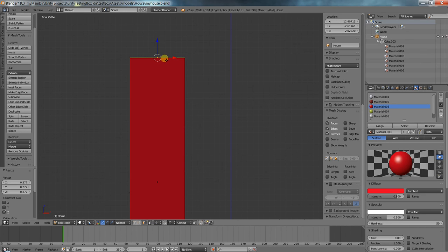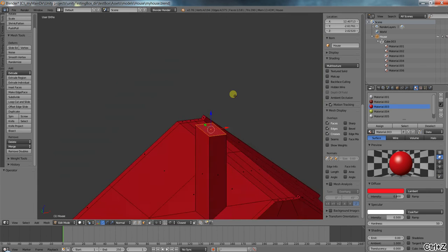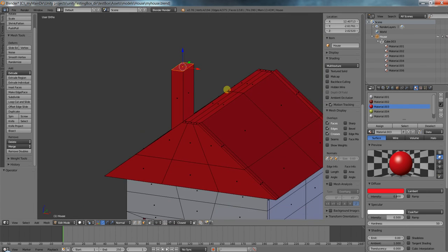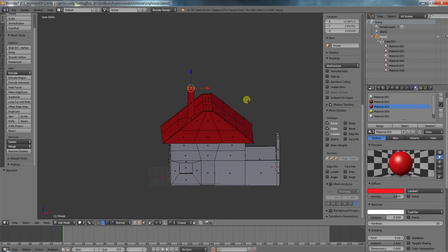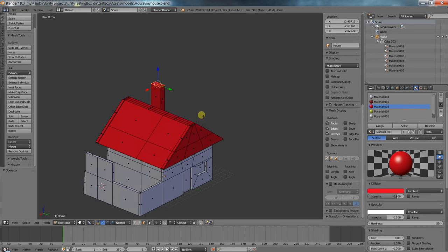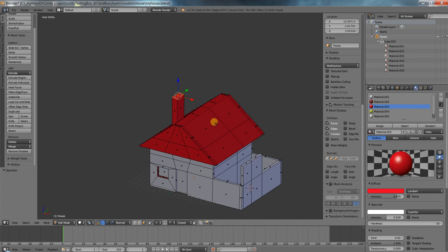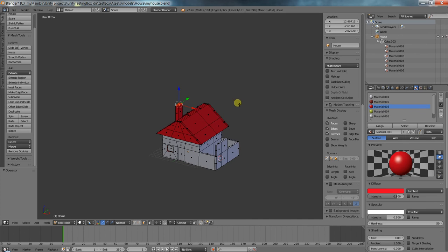It's not completely 0. Same as scaling 2 points close to each other. You can scale as much as you want. AutoCAD will always tell you it's a fraction. It's not flat. Alright, so this was scaling to do other things than just scaling: scaling to merge points and scaling to flatten things out.